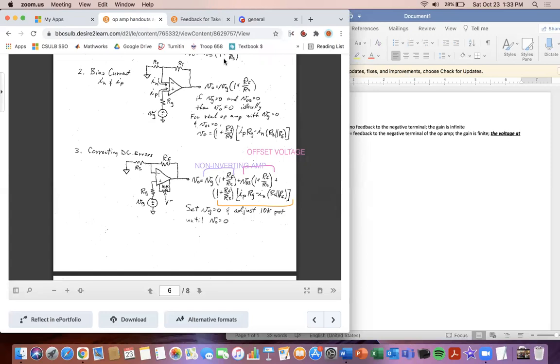And the one in orange here is going to be for your bias current equations. So that takes into account all the possible errors that you can get. And so what happens is he says right here is to limit the amount of errors you can get read due to this offset voltage and due to the input bias current when VG is 0. So these two right here are the ones that would cause errors within your readings, this offset voltage and this input bias current. If you set VG equals 0, so we have no non-inverting amp right here, these two